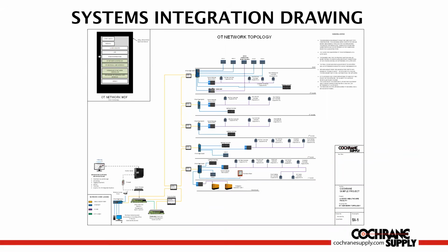So when you're laying out an OT network, there's several steps to it, but as long as you understand the hardware that's involved, the cybersecurity concerns that are there if you're connecting remotely, and if the owner does tell you that, hey, we still want to see this stuff on our network, then you're only connecting in one place, and they can manage the VPN connections and all that good stuff. But the integrated systems out here in the building, those all sit on one network, your OT network.